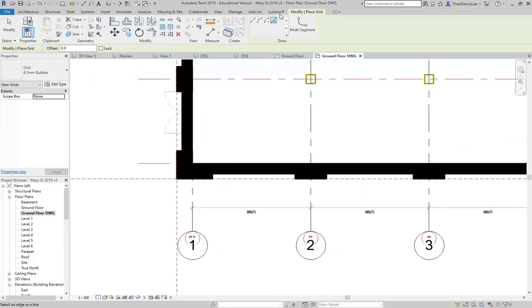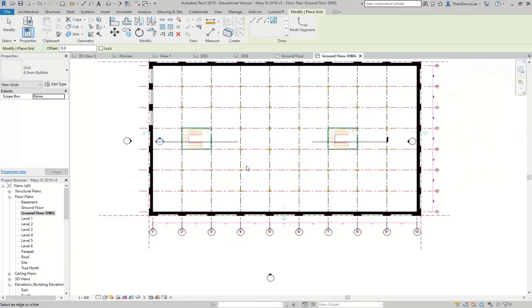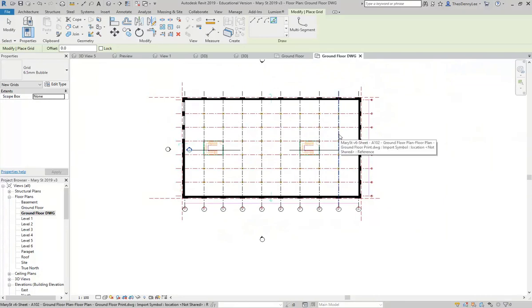So you just have pick lines. You've got to use the grid tool, and then you go to pick lines. So click the grid button, and then choose pick lines. And then just pick those grid lines. So you then just pick each of the grid lines. And then you'll see the numbers go over the top just like mine. Yep. So there should be 10 of them.